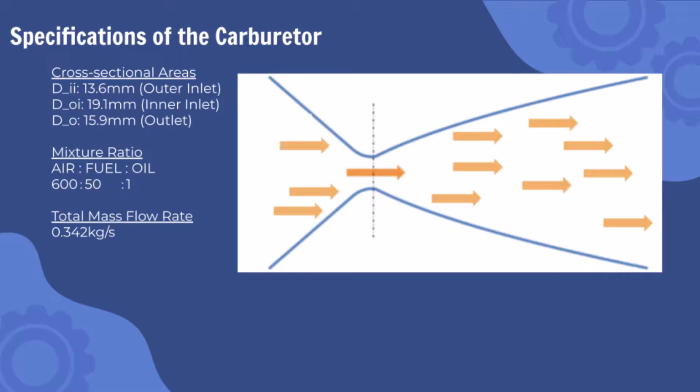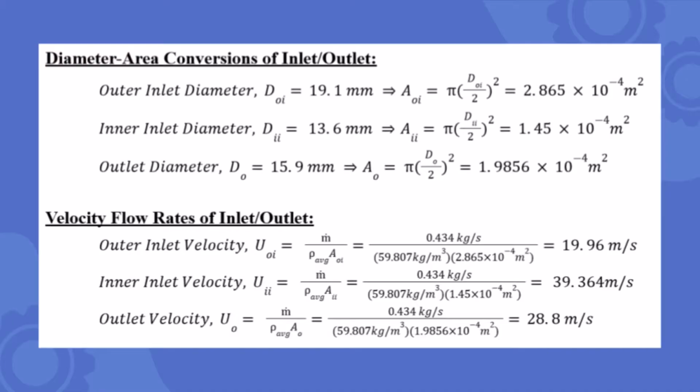The main fluid mechanical aspect of a carburetor is the exchange of pressure and speed due to the geometry of the Venturi, which allows the fuel to be sucked into the carburetor and mixed with the other reactants. This pressure change in the carburetor was determined using the mass flow rate and the change in inlet and outlet areas due to the Venturi. Beginning at the inlet of the carburetor, the inlet pressure could not be assumed to be atmospheric due to the pressure having a non-negligible velocity.